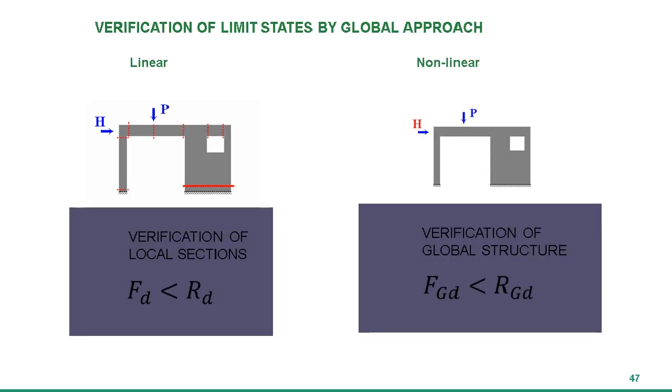So these energy-based principles are very important to be incorporated into any finite element analysis which is being used for these kind of brittle materials, like concrete. So let me now talk about these safety formats available for nonlinear analysis. The formats that I will be presenting are part of the FIB model code, which was proposed in 2010.